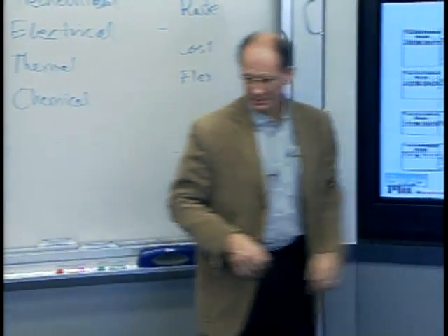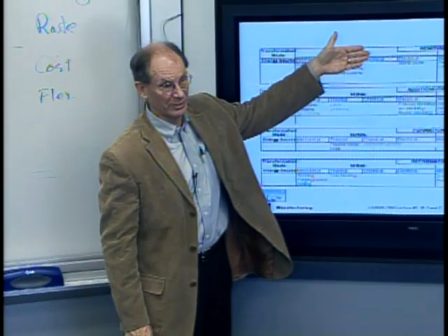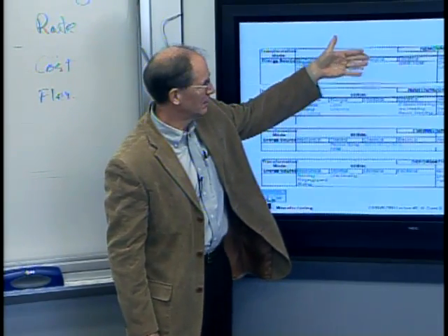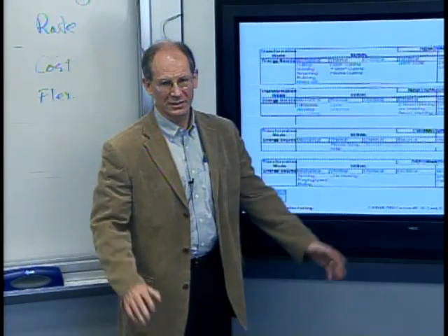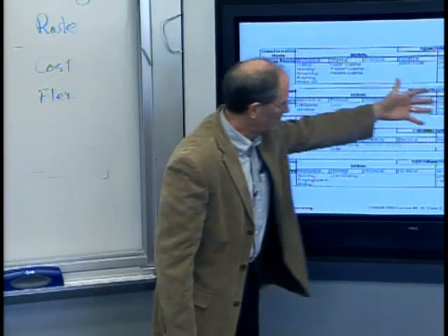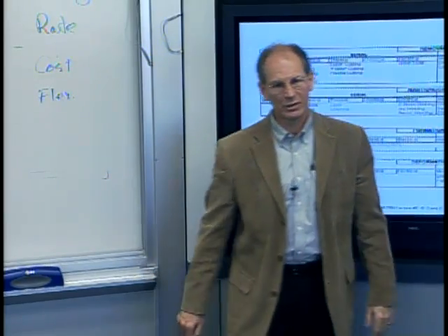So if I look just at this purely serial parallel thing, yeah, serial's better than parallel. I think we can show in general that removal tends to be the least sensitive to material properties, the least sensitive to all these things. So serial removal kind of wins in most cases in terms of flexibility. Deformation is generally a killer in terms of flexibility for these reasons that we've talked about. And in many cases, certainly anything that involves a parallel energy exchange starts off behind the eight ball with respect to flexibility.